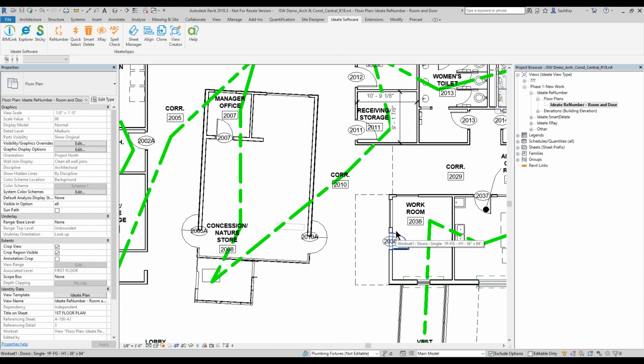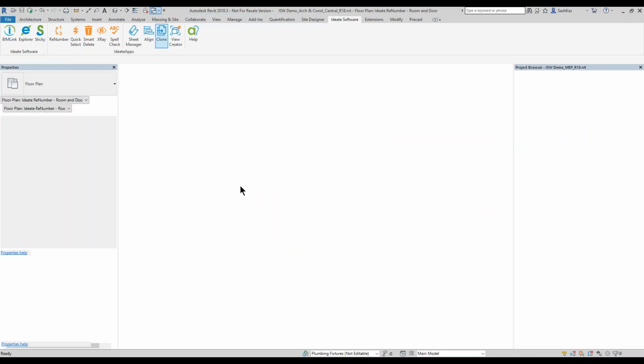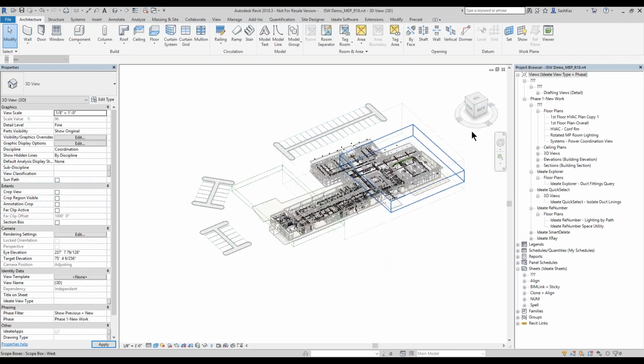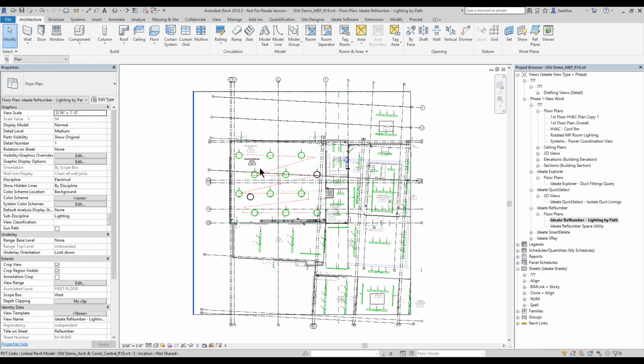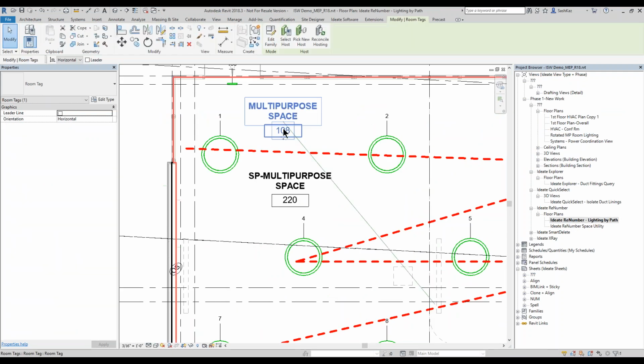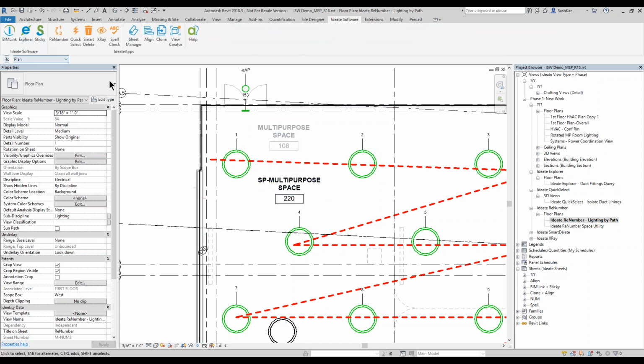And again, you can make a lot of rules if you want. So that's an example of that. And real quickly, you can also do the same thing for light fixtures. As I mentioned before, you can do light fixtures by path. So if I look over here, we have a room that's from an architectural link, and we have a space which is actually in here. And I can use the room information from the link to renumber my spaces. And I'll just show you that real quickly in this MEP model, and then I'll move on.